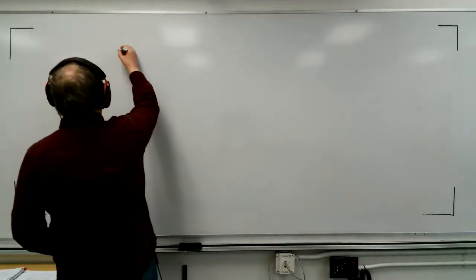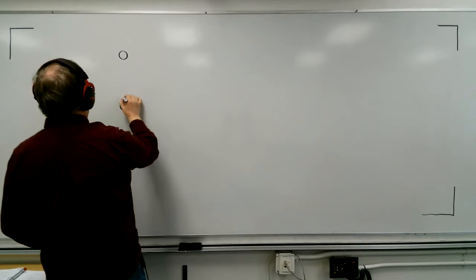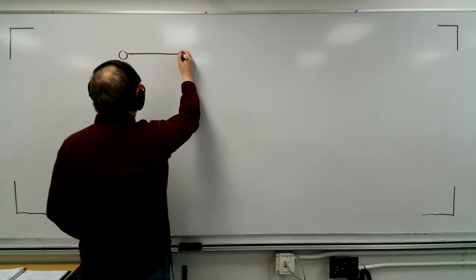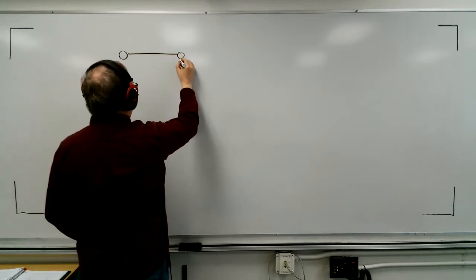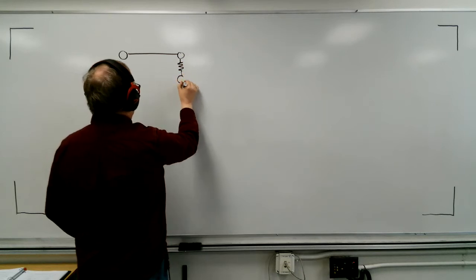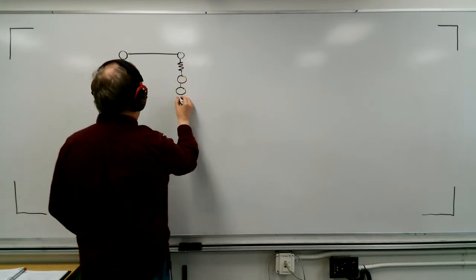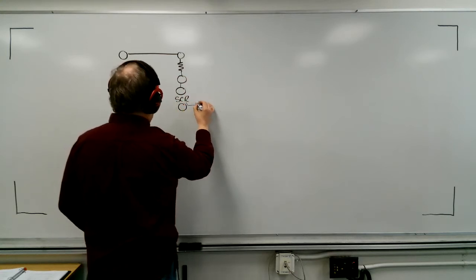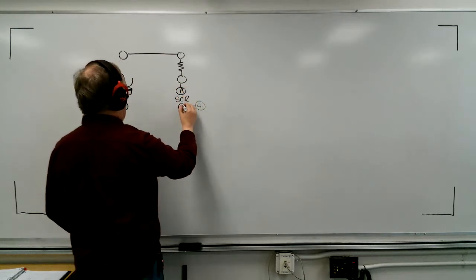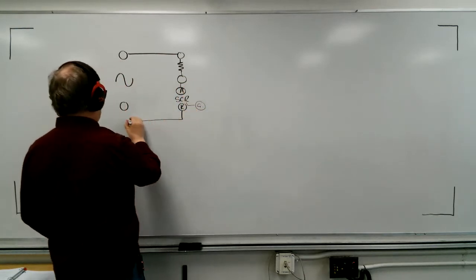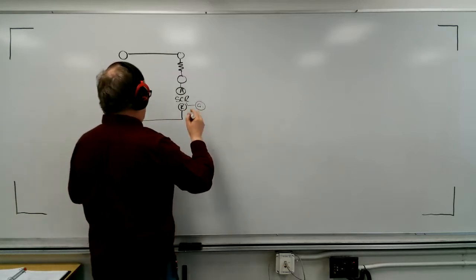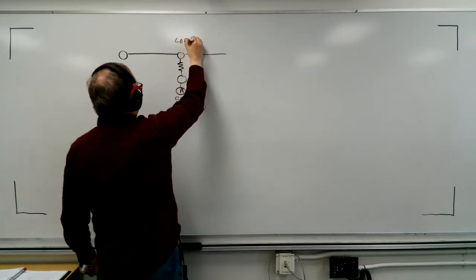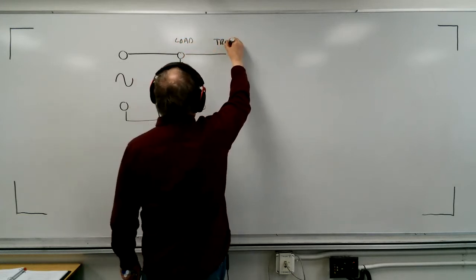So the half wave looked like this. Here we had an AC source. We came in like this. We had our load. Then we had our SCR. And over here was the gate. Anode, cathode. And then we came back, and that went back to the source. Also attached to this was the load part, right? Load. And here was the trigger circuit.